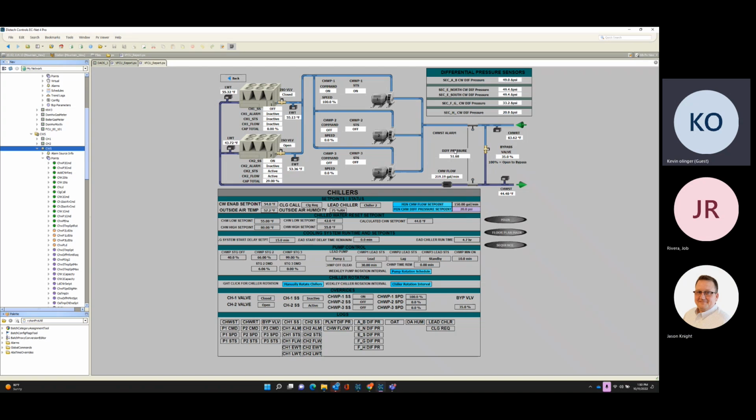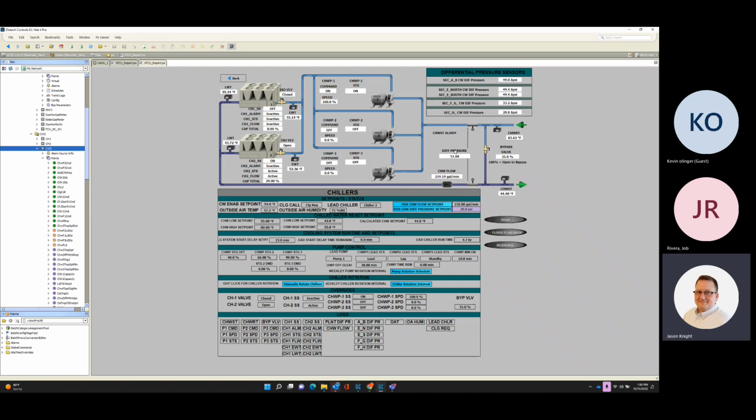Right. So where are we at with SCC and Collins? I guess it doesn't matter what Collins' final role is, but do you know where we're at with test and balance and commissioning from SCC? The test and balance is done. SCC did some TAB verification, and last week there were some questions about some airflow missing on DOAS 7, and these car dampers that Daryl wasn't accounting for, which was like 3,000 or 4,000 CFM.